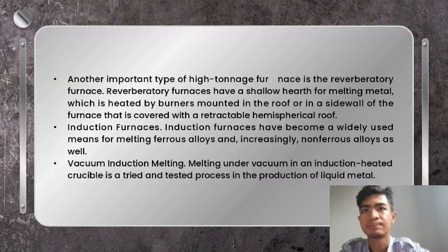A wide range of metals can be melted with this type of furnace, though little refining of the metal is possible. Induction melting is performed by applying an alternating current through an induction coil, which produces a magnetic field that generates a current flow in the charged material through mutual induction. This generates heat in the metal. The amount of energy absorbed by the charge depends on the magnetic field intensity.